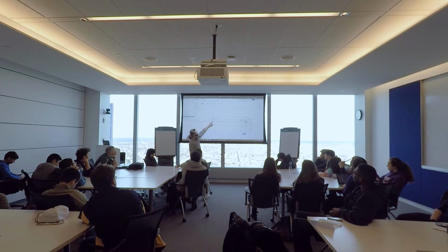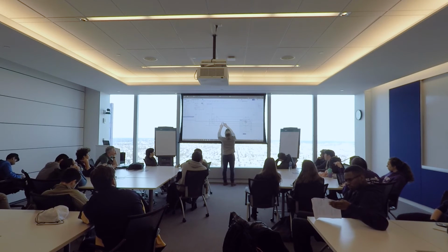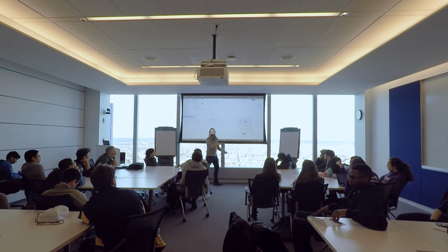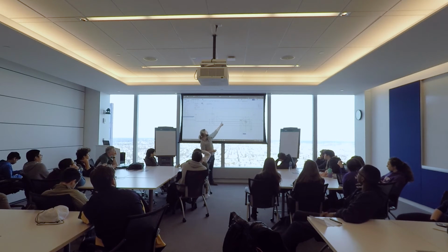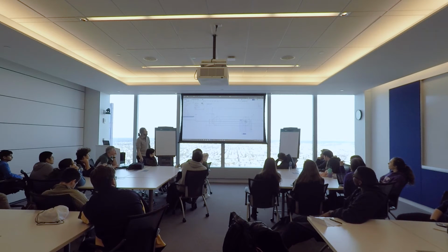The tricky thing here is to make sure that this isn't a vertical dimension. This is a dimension that's actually parallel to this line here. It's very important because if it's not parallel to this line, if it's not a slightly projected angle, you're going to have the incorrect center to center spacing on that chain setup.